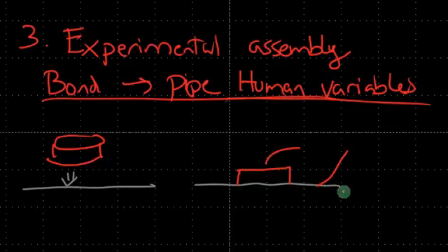Here, if this was metal, you can just attach one lead here, and assuming that some point of this is not bonded, the metal actually touches the electrode. You may have to pull out some type of thin electrode from the very edge if you have a non-metallic surface you bonded to, or if your bonding layer is thick. But if your bonding layer is really thin, there's probably some portion of the metal sheet which is touching your bottom electrode of your piezo, because piezos have electrodes on top and bottom.